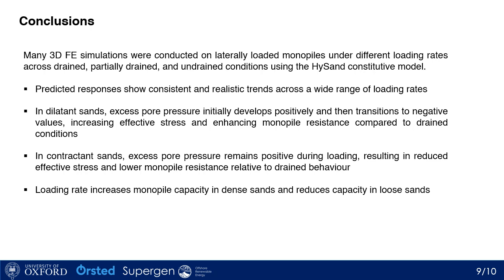For the dense sand with dilatant behavior, excess pore pressure initially develops positively and then transitions to negative values because of the phase transformation. It increases effective stress and enhances monopile resistance compared with drained condition.